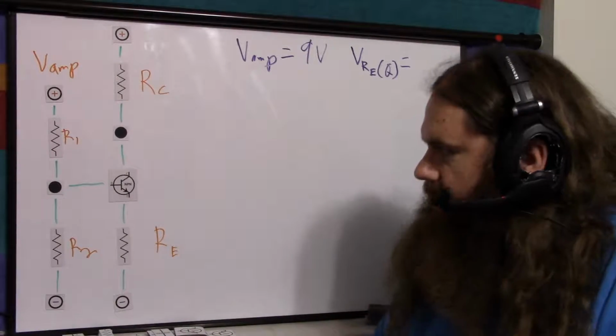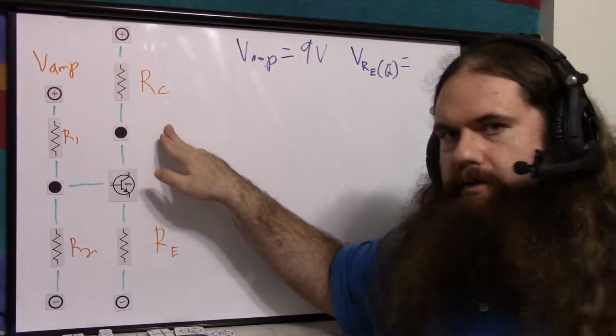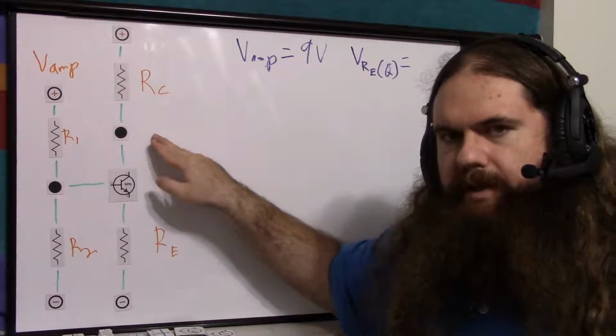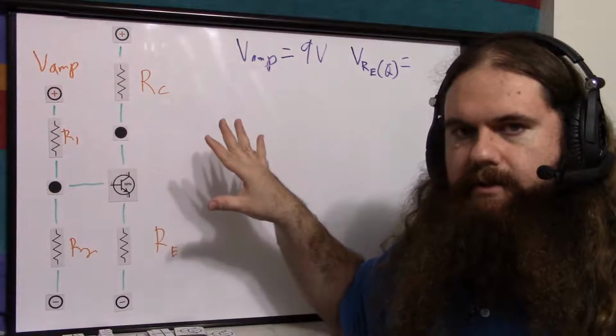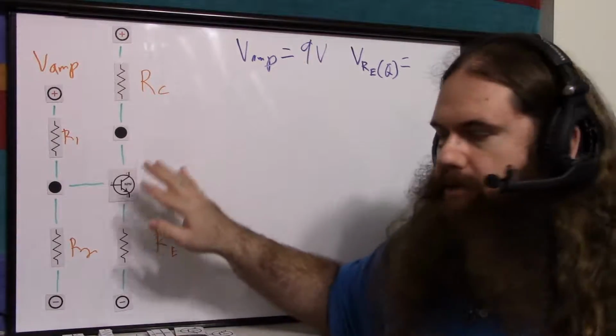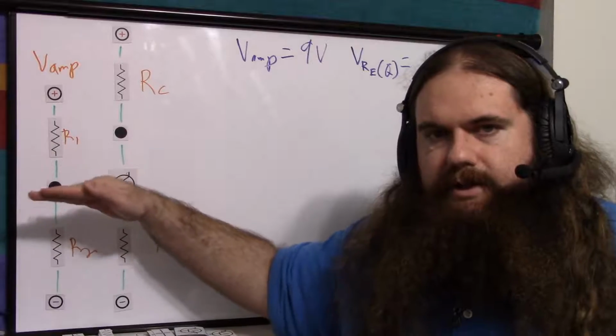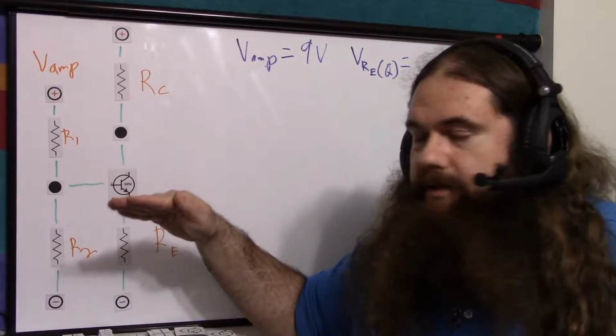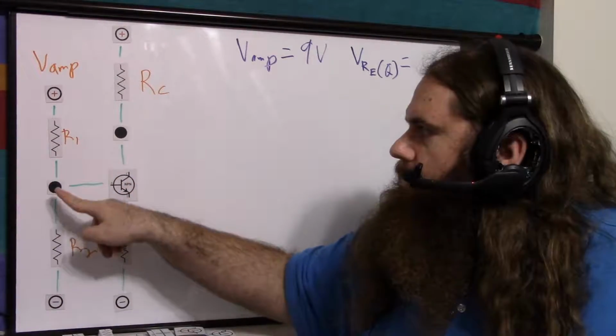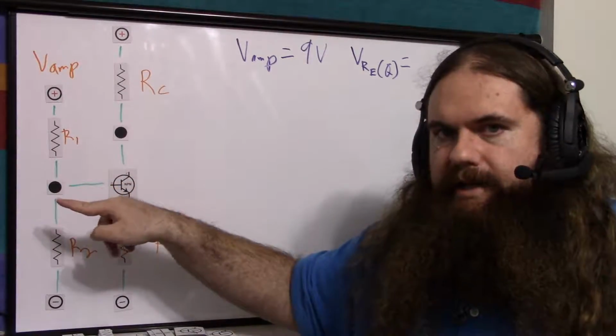This is the quiescent state. No input plugged in, no output plugged in. Now the output being plugged in only changes the impedance really, so we'll not worry about that too much. The input not being plugged in just means the signal is effectively always 0, because the input signal just pushes with or against the bias.